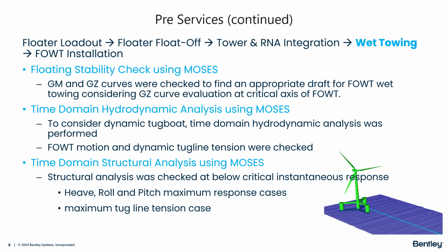Structural stability was also evaluated by identifying the most critical time steps based on the structural loads. For example, critical moments may occur during maximum floater motion or when the towing line experiences peak tension. Load cases were generated for these critical time steps, followed by structural analysis and code check to ensure their stability.